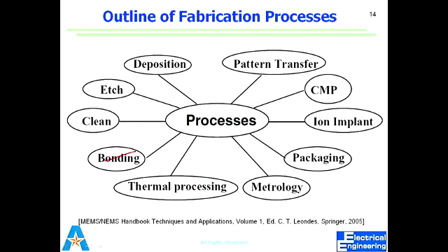When I have to fix something, and I have a bolt and I have a nut, they have to align to go in, right? So now, if this was my surface, and I did lithography and I exposed, I just did doping and I defined a resistor within the bulk. Now in the next layer, I have to make connections. I have to get the lead out from the edges, right? I don't want it to come from the center. I don't want one lead to come from here, another from here, because that's not going to connect my resistor. So I have these two leads to be exactly coming from this place. So the next mask, which is going to define the placement of a lead, has to be aligned very well with the first layer.